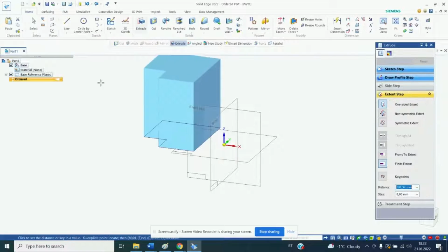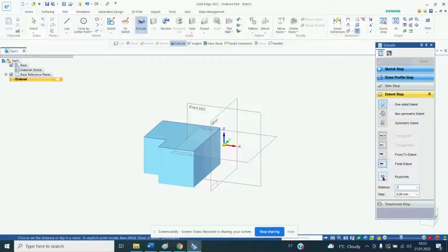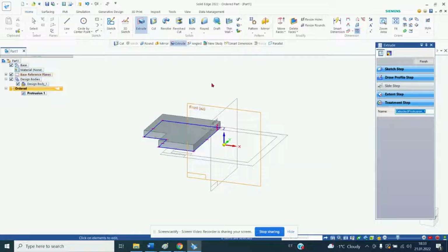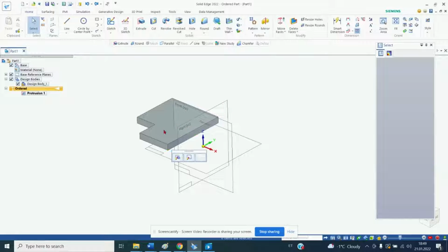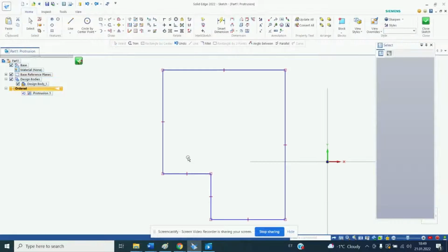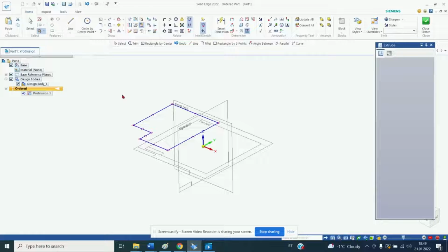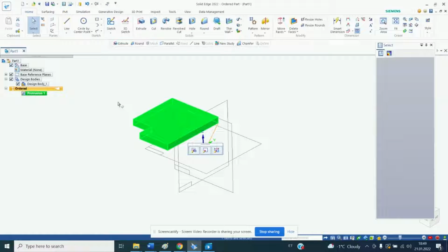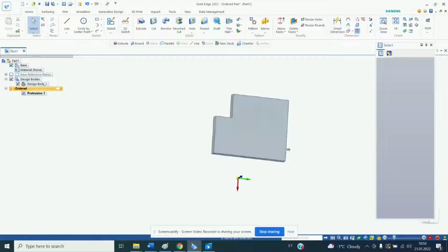Now we can give thickness to our drawing. Let's make it 10 mm thick. If you want to edit the drawing, then click on Model and select Edit Profile. It takes us back to the extruded environment. To make the drawing clear, unselect base planes in the menu on the left. You can zoom in and out using the mouse roller and change the viewing point when holding down the mouse roller button.